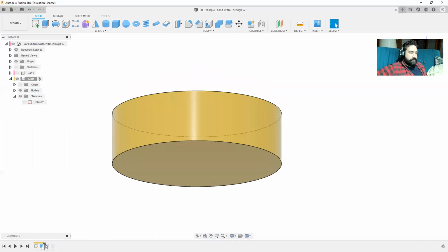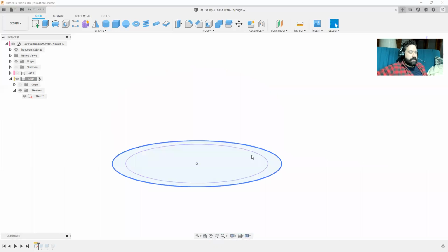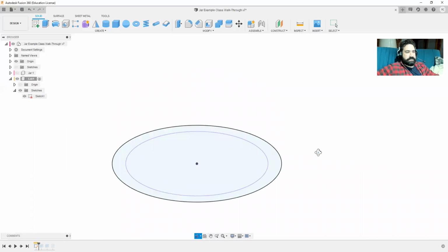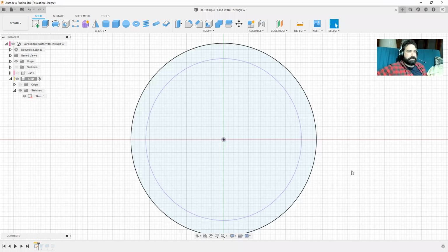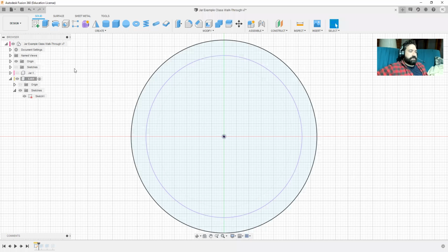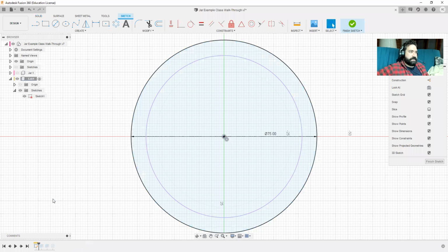I'm going to go back before the threads, and before I extruded that outer ring, and of course I have to unhide the sketch. I'm going to use this sketch here to build my texture into automatically. So I'm going to go back into the sketch, because I don't want to add an additional sketch, because I still want, when I slide back forward in history, this modification to be already incorporated into it. So I'm going to edit my sketch.